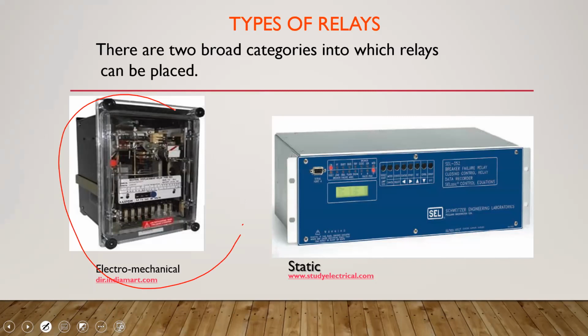Okay, the one on the left, I'm not able to read the writing on it, but I believe it is an overcurrent relay. Now, that relay would be monitoring one phase of your power line, for example. So for me to monitor an entire line, the 3 phases, I would need one of these on the left per phase.